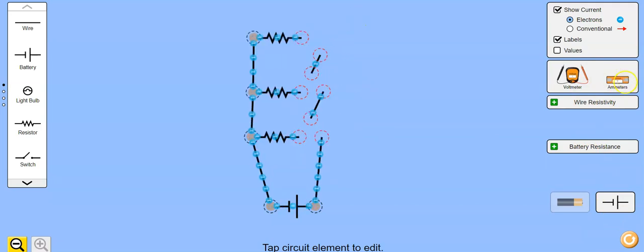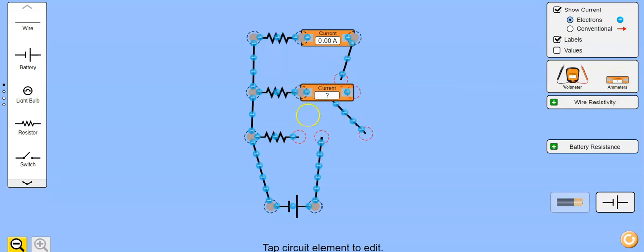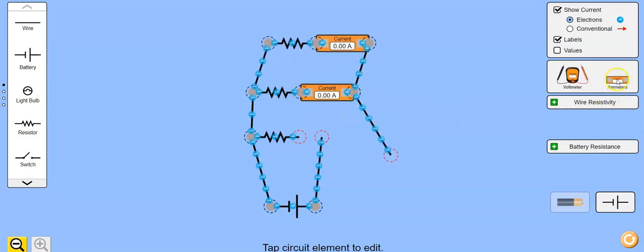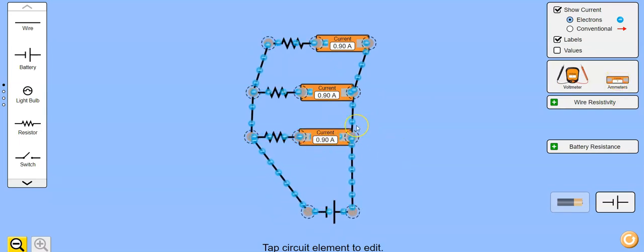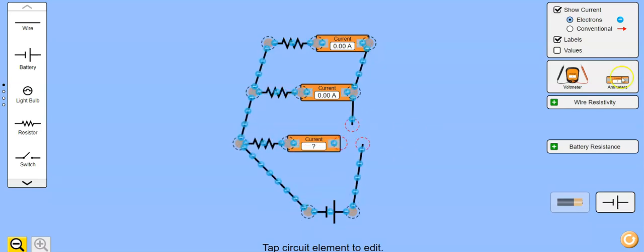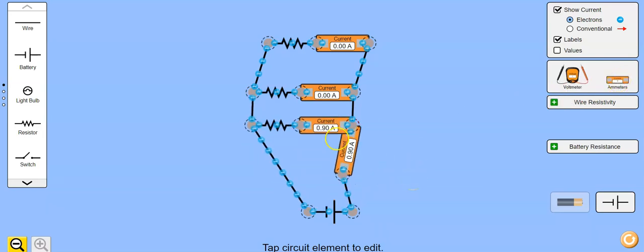All right. So in terms of taking measurements, it's very similar to the series circuit. So you put your ammeters in different spots. For this one, you do want to take current for each branch, okay? Because you want to see what's happening in each branch of the circuit. So you'll do this. There we go. And you really do want to have one more because I do want you to take total current as well. So you'll put an ammeter like that as well.